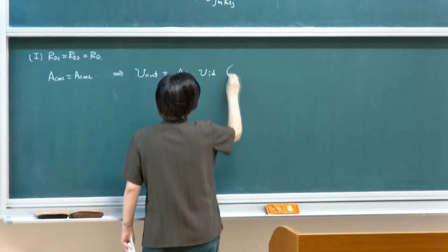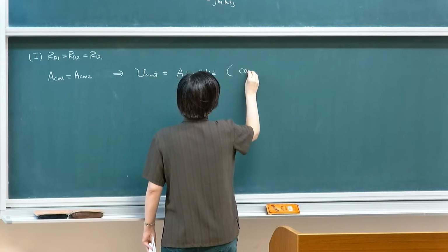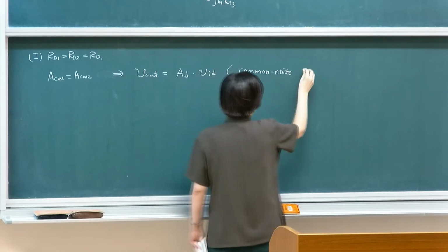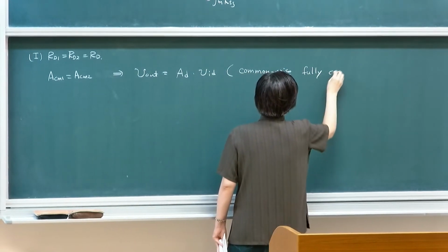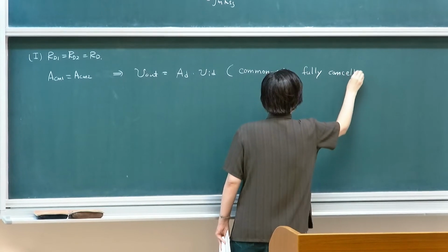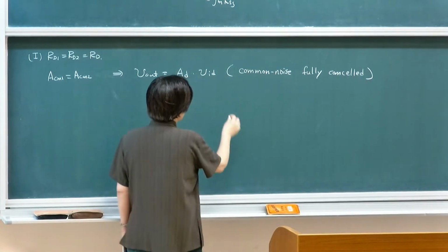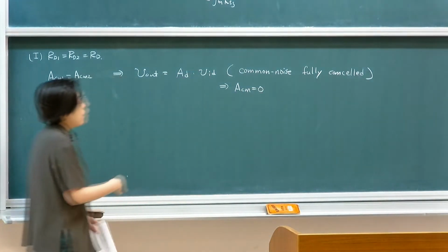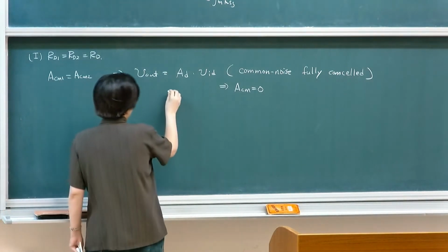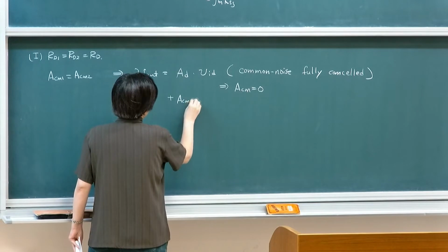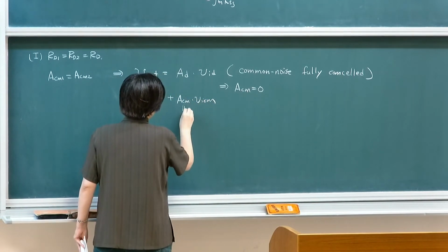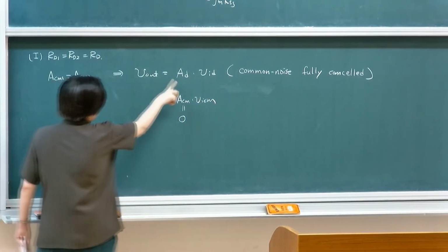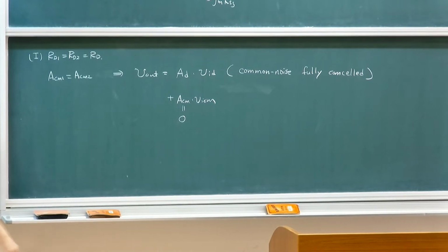So in this case, we should say that the common mode noise is fully canceled. In this case, we can assume that the common mode gain is 0 because you don't actually see any amplification. So you can rewrite it as ACM times VICM, where ACM equals 0, right? Your overall differential output Vout will then give you that.